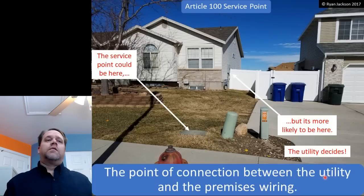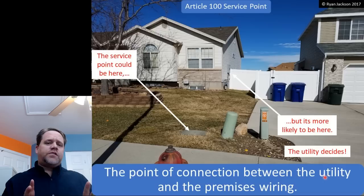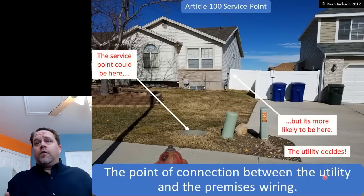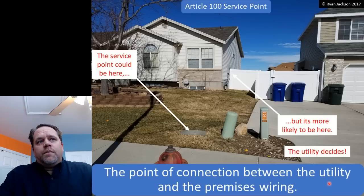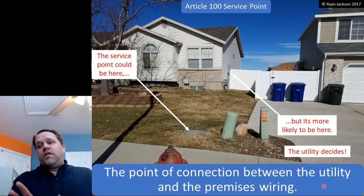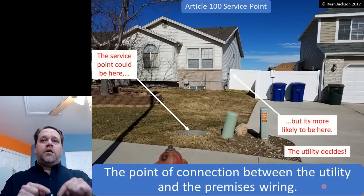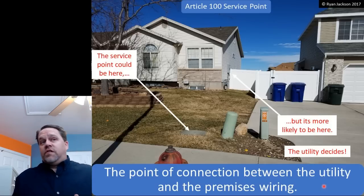Well, a service point is one of the most critical definitions in the entire NEC. And it's such a simple definition that it's difficult because it's so easy. And I know that sounds kind of dumb, but let me tell you what I mean by that. The service point is the point of connection between the utility and the premises wiring. The service point is where the utility says, we're going to end here, and now it's yours. That's the service point. Wherever the utility says it is.